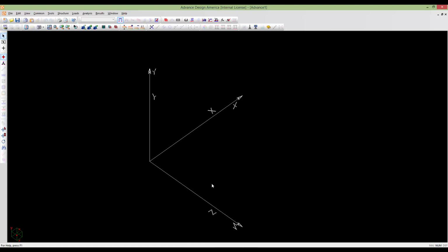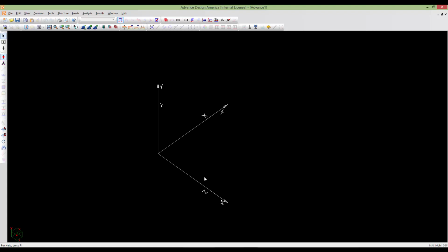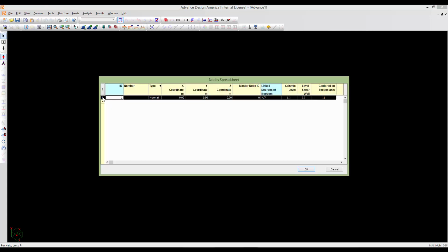Okay, the next stage will be to define the geometry of my beam. In this session, we will only discuss the one-dimensional beam, or simplified modeling and design, in which we only consider one beam. To define this composite beam or girder of the bridge, I'm going to define the nodes first. So activate the node mode, Control H, and here I will define the nodes.